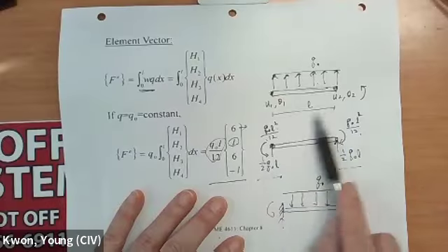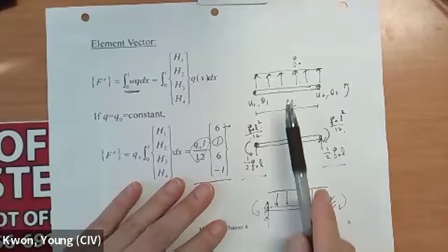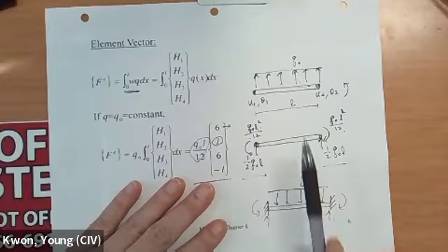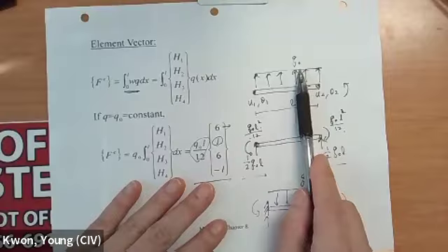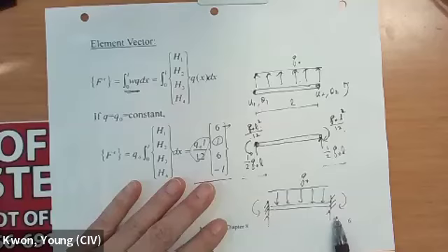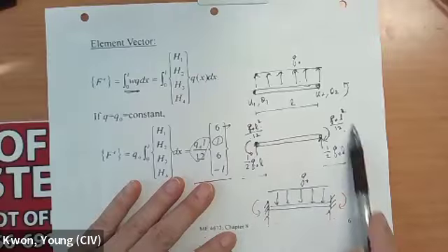And the physical meaning of this force and moment, as I explained, is this: when you have a beam clamped at both ends, and let's say you apply the opposite load of this Q, a downward direction, then the supporting condition at the right side, if you solve this statically indeterminate problem, the reaction force and reaction moment are exactly the same as this one.